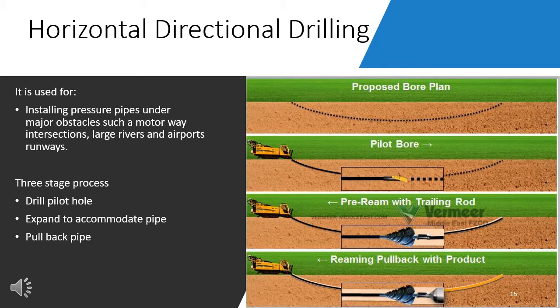The second stage, here the pilot hole is enlarged to the desired diameter to accommodate the utility line that will pass through it. Now, this utility line is then put into the drilled tunnel. As the pilot hole is being drilled, a bentonite drilling mud is pumped down the center of the drill rod. Here, the drill head consists of either a jetting head or a drill bit. Before the start of back reaming, the pipeline must be positioned on rollers in line with the hole to minimize any axial load on the line.